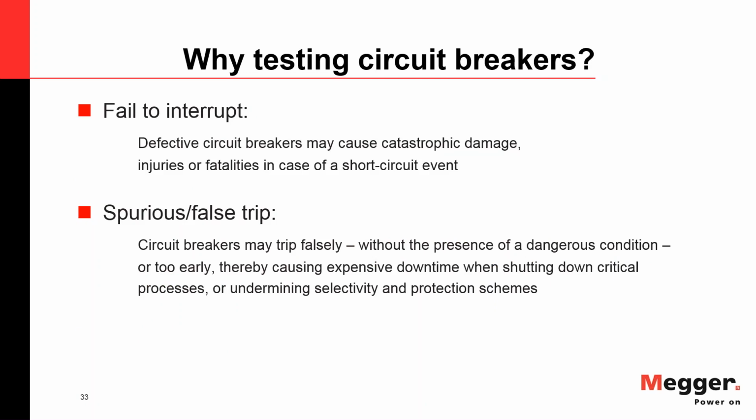For me personally, I would make it mandatory that every person that works in the power industry goes to a test lab and watches some of the interruptions and some of the testing that is being done during the type testing. Because once you see what happens when a circuit breaker interrupts or fails, there's no discussion about why are we testing and should we test. Nobody wants to be in front of a fireball and be killed by that.